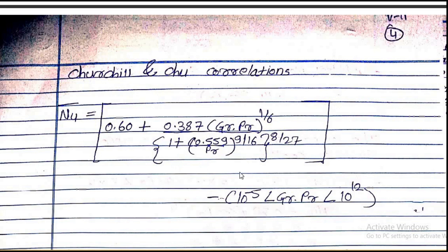So this equation we can apply for the product of Grashof number and Prandtl number greater than 10 raised to minus 5 and less than 10 raised to 12.